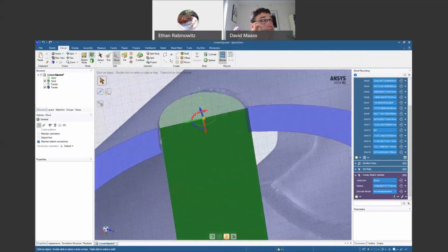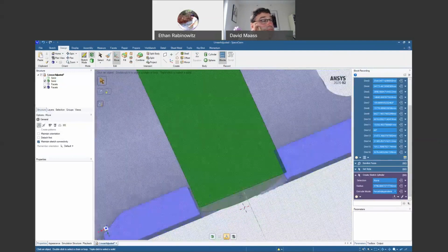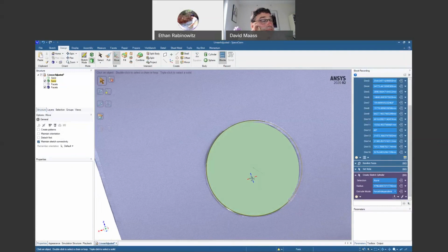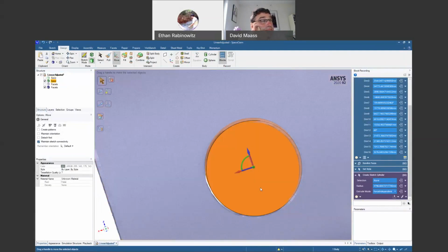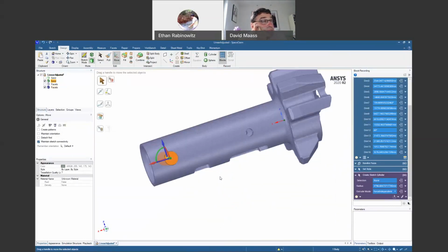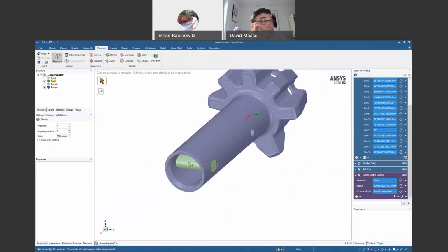But all in all, it looks like it may be off-centered a little bit. So I could just grab that solid body, and with the move tool, I could translate it around. Obviously I don't need to rotate it in this direction. And actually, let's just take a look at something. Let's do a quick measurement between the cylinder, the face, and the y-axis. Let me scroll and grab that axis there. So we'll measure between the axis and this axis.